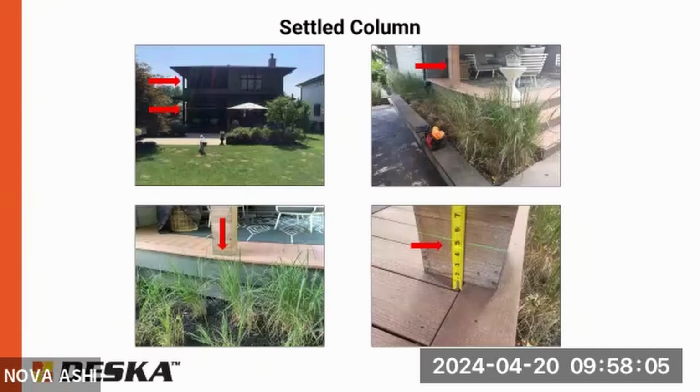An inspector could come out, they could probe the ground, and it may seem okay, but after it goes through iterations of rain and the elements, that soil will tend to settle quite a bit. If you've ever dug a hole and then backfilled the hole, and then you come back a month later, there's a big divot in the ground where that soil has settled.